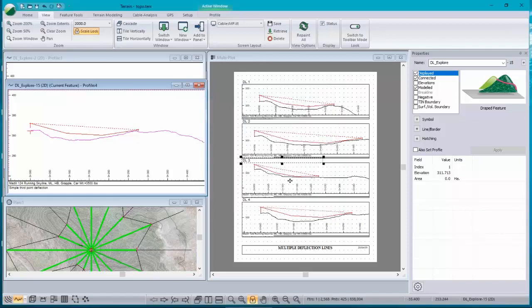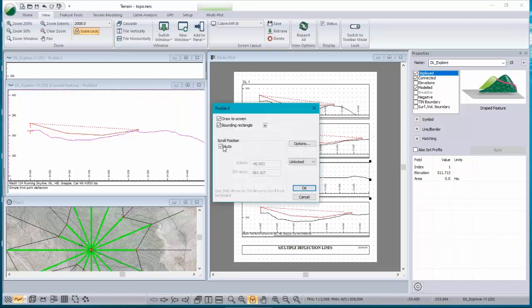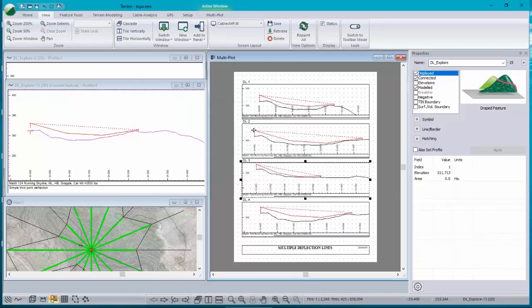So one more thing, if I wanted to make them all line up, I could turn off this auto thing here and put in a nice even number for offset. Whoops, that would be a negative number for offset. If I did that for all of them, they'd all be lined up starting at 0, 50 meters from the edge.